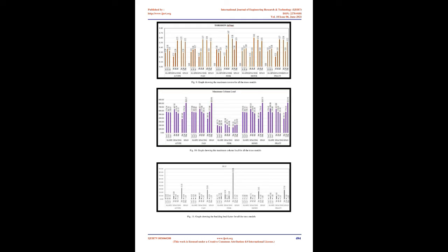Collating all truss types, maximum displacement is observed for models with slope 1 in 3, 6 m spacing and span 18 m. In the corresponding specification of maximum displacement, slope and spacing possessed minimum to moderate range of values mentioned in the study. With this deduction, it is clearly elucidated that span is the most influential parameter, as the maximum value of span adopted in the study induced extreme status of displacement for all truss types. The parametric specification of slope 1 in 3, spacing 4 m, and span 12 m seemed more economical in having lesser displacement, and Fan and Pratt trusses are observed as reasonable.